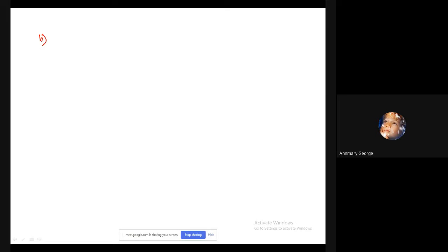This is called depth of velocity modulation. Please write down the equation of depth of velocity modulation. Depth of velocity modulation can be found out by beta I into V1 by V0. Okay, this is the equation. Please write this equation.